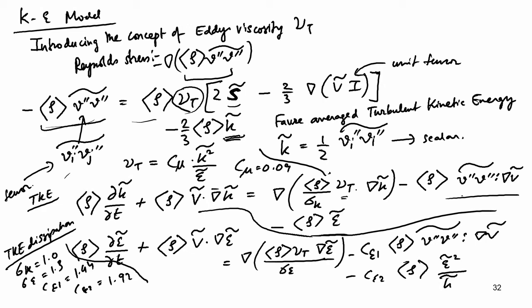is equal to 1.0. These are the different model constants that are typically used in commercial softwares. Okay. So, to summarize, here we are trying to deal with the flow. To deal with the flow you need to solve at least two equations, the continuity equation and the momentum equation. In non-reacting, constant density flows in CFD you do not directly solve the continuity equation. It comes from the pressure potential equation from the momentum equation itself, and then you implement the divergence of V equal to 0 criterion.